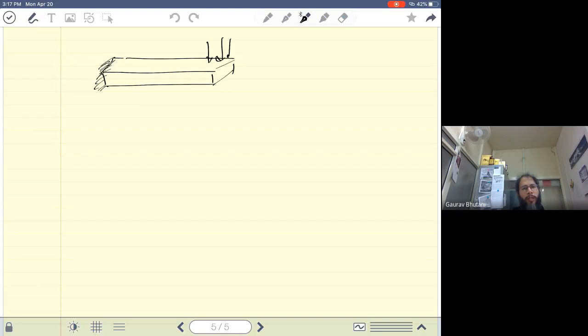If I take a point P on the top surface, I would want to figure out what the strain value at point P is for a given deformation when a person stands on the right-hand side. As an engineer, you would want to quantify the value of strain. You will want to put 9 numbers there. But how do you measure that? It's extremely difficult to measure shear strains because these are changes in angles in certain planes, and it is not very straightforward to measure that. But measuring elongation is very straightforward. So what we do is use something called a strain gauge.